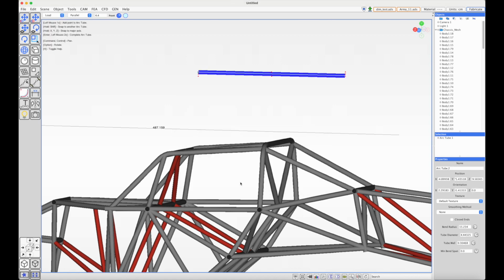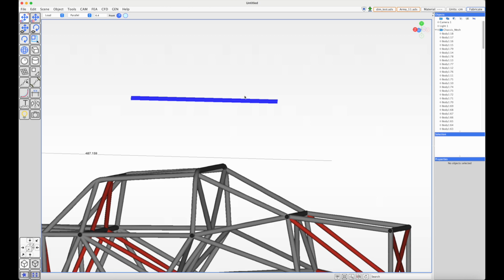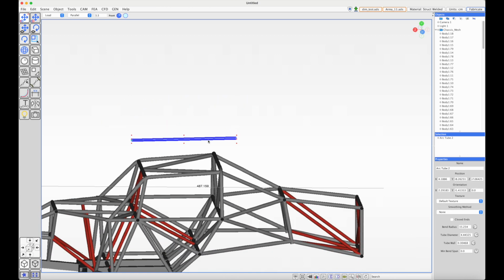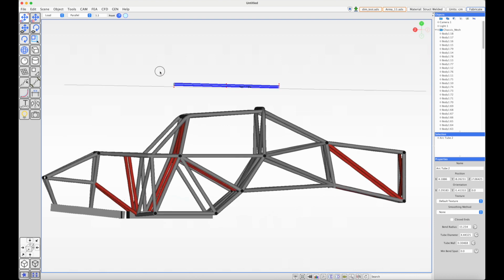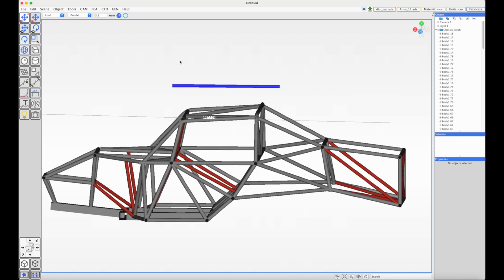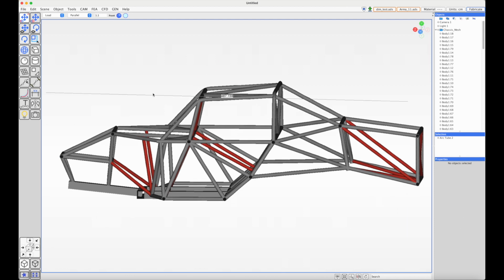There we go. So you can see the 1 3/4 inch tube looks like the scale is correct. So we've set in the project file the units that we want for the file that we've imported. I'm going to get rid of this. We don't actually need the dimension. So I'm going to save the file just so that we have it while we work.